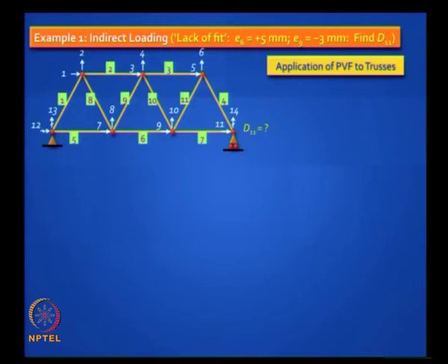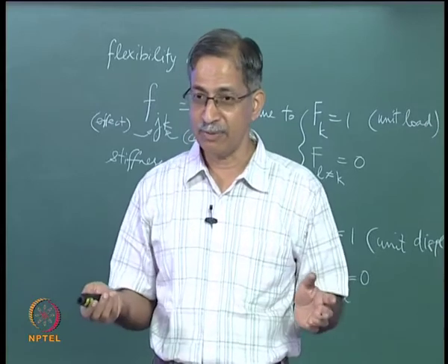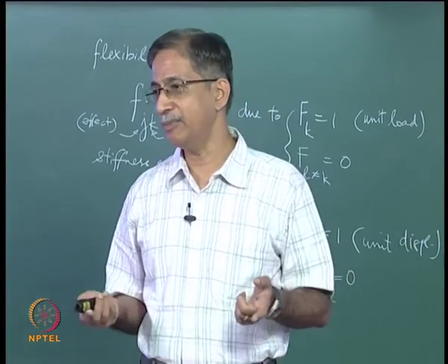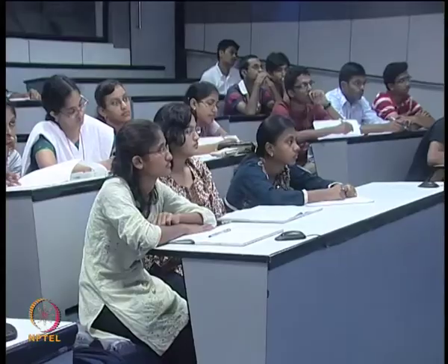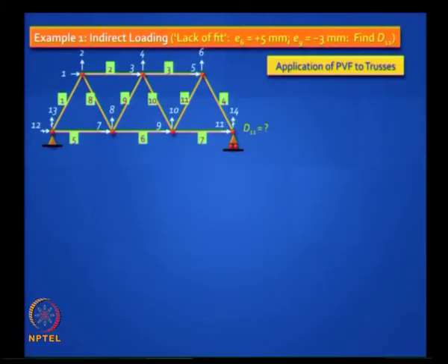Will you get any internal forces when you do this? No, because you have a just rigid system. The bars will just move about a little bit, there will be no support reactions, no internal forces. But if the structure was over rigid, it is possible that you have support reactions, you have a self equilibrating system, right. Now, the question is, can you find the horizontal deflection D11? How much will that joint move to the right? This is D11.